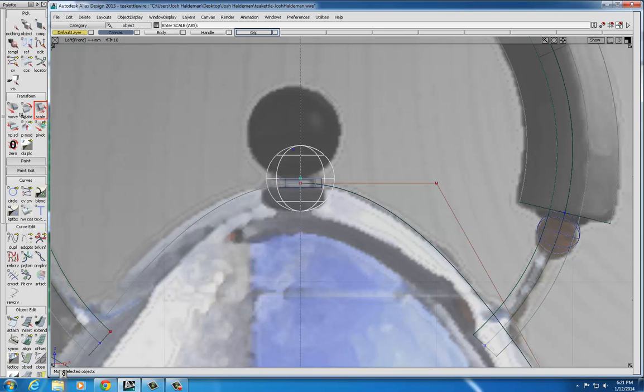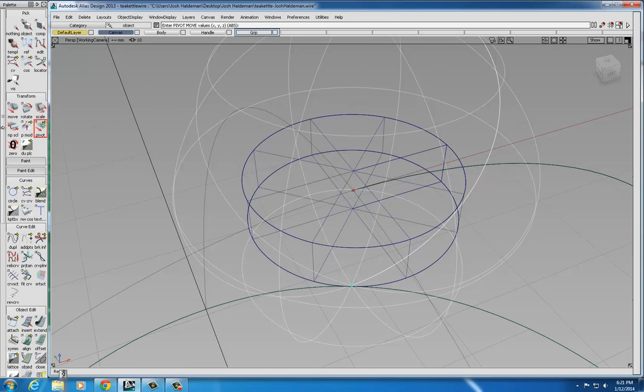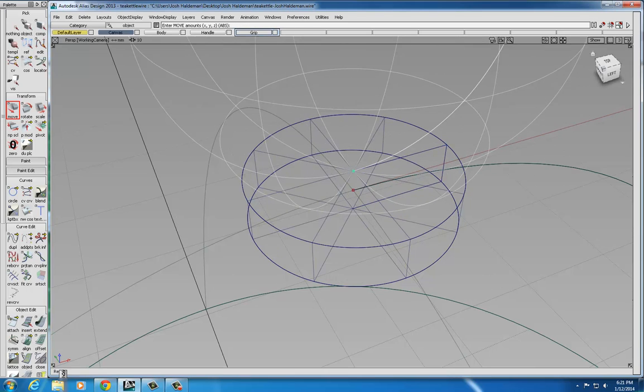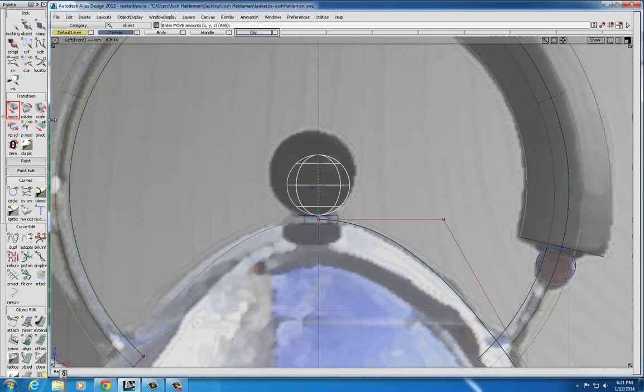It's still a little small, but before we resize it so that we can make sure we get it right, let's move the pivot point on this axis all the way to the bottom, and then reposition our sphere on top of the cylinder. So I'm moving it again. Curve snap still needs to be on, and then snapping again to the center point. Now that'll put my sphere where it needs to be, and it has the added advantage that when I scale it, it'll scale up from that point. So now I can tell exactly how tall to make my sphere, and it's also the right width because I'm scaling universally using the left mouse button.